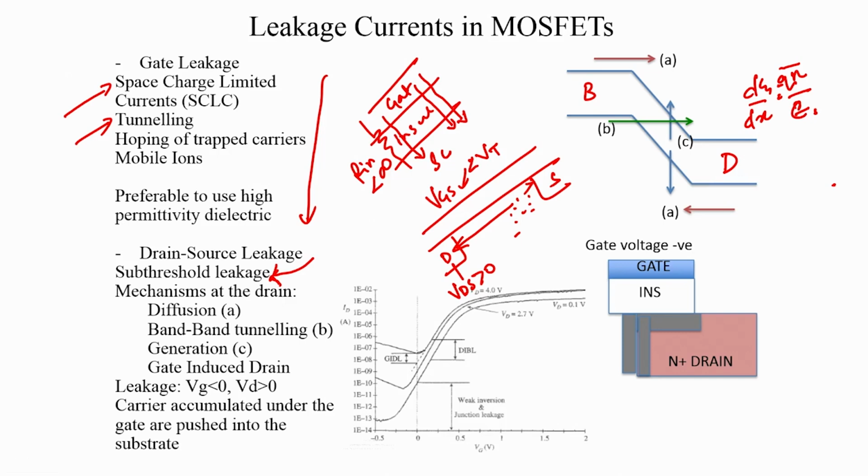And this p-n junction is reverse biased, okay, and near the source side it is not, depending on the body to source potential. Now, all mechanisms that contribute to currents in a p-n junction also contribute to currents in a MOSFET that is turned off, okay. And what are those mechanisms? You do have diffusion across from the p type body and the n type drain.